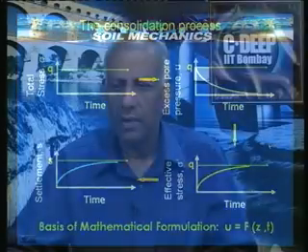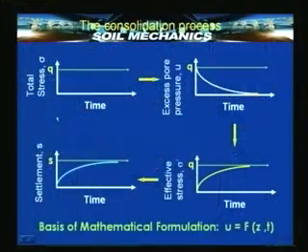To sum up all this, what we can say is the total stress is equal to q at time t equal to 0, and it remains constant at all times, because total stress is equal to the pore pressure plus the effective stress.